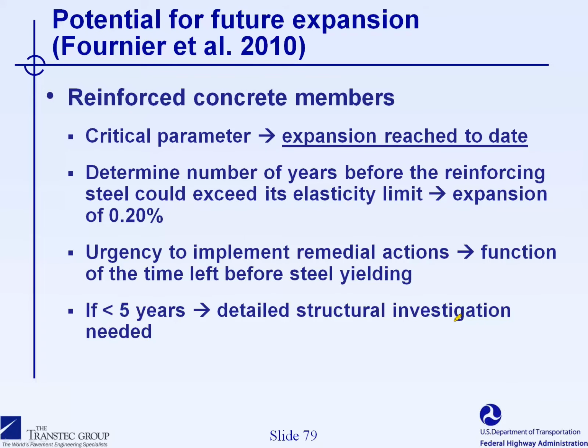But for the final interpretation of the results, it is important to determine what is the critical structural effect of ASR in concrete members. And in the guideline document, we are providing some suggestions in order to do the interpretation of the results of testing, especially the residual expansion testing.